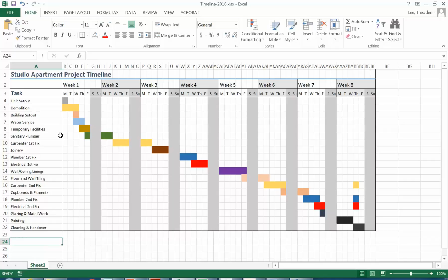When you're doing areas, always, when you're doing your own designs, you should know the overall area of the proposal. For a development application, you'll always need to give a floor space area, which is actually the area to the outside face of the walls. It's not just the area of the floors. So you do need to go to the exterior face of your walls. And then you'll need to give that as a ratio to the site area. That's known as a floor space ratio. So it's the ratio of the floor space to the total site area.